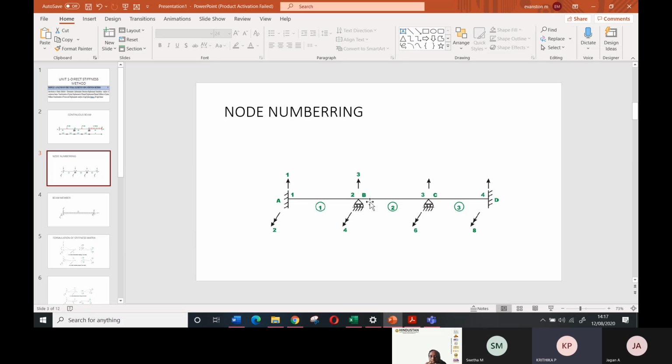So you understood the concept of the 3 different supports. In practice, a fixed support is a beam-column joint. Simply supported is when the beam is resting on a brick wall. Have you ever noticed a beam resting on a brick wall? In my house, it's a non-load bearing structure, not a frame structure, but we built a frame with a beam in the car parking. One end of the beam rests on the wall and the other end is on the column. So it is a propped cantilever. Have you come across the word propped cantilever?